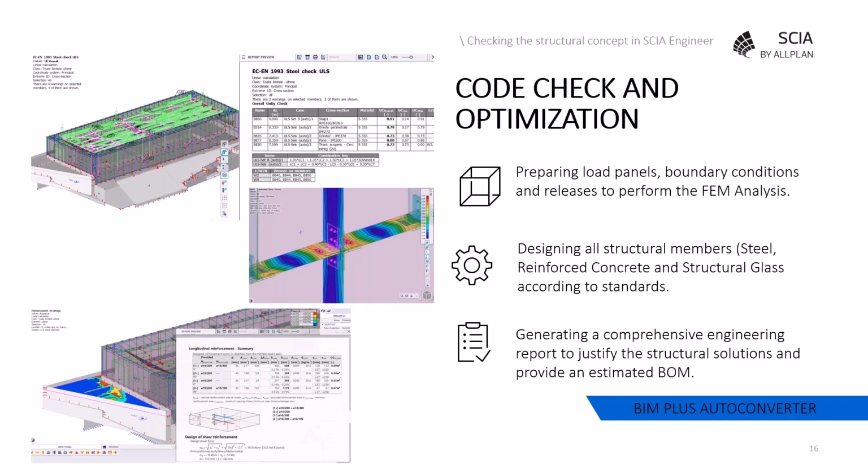And the idea is that we can see exactly what resources we have and what is the utilization of each structural member. So this is how we can make economy. So we can decide to limit somehow the number of cross sections, but at the same time we can see if an element is over designed, under designed, and if there are any resources left to make some economy in case we have this value engineering or have some pressure for contractor.